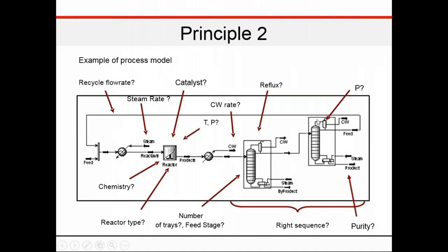Why? Because some of the gases that may be collected here may still have some content of crude or of oil or impurities in it. So it will be brought back into the system. That's why we call it what? A recycle flow rate. So that is a recycle for you. This is a typical example of what happens in HYSYS simulation. What we have here is now a purer component around this point.